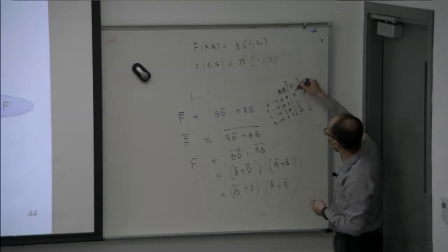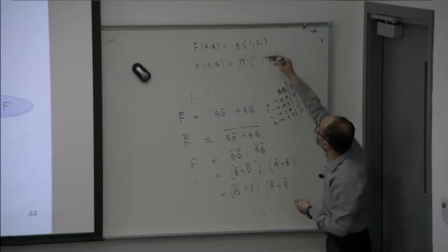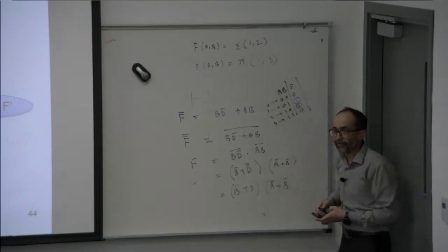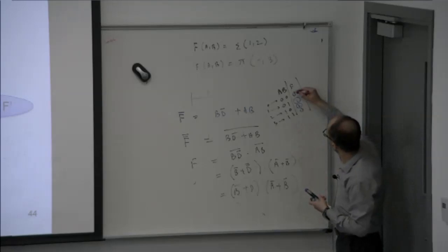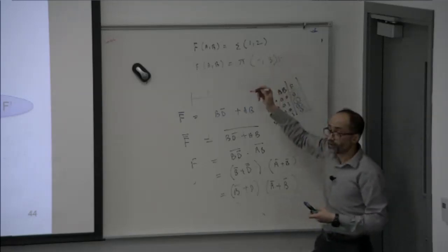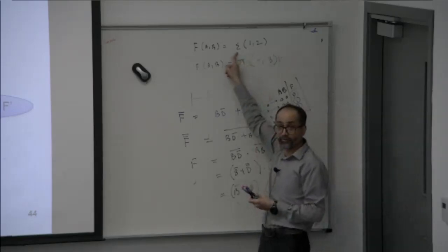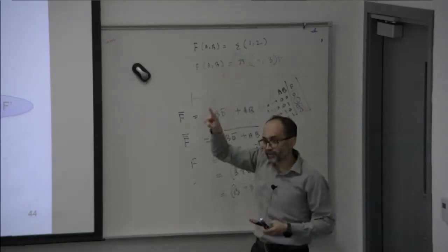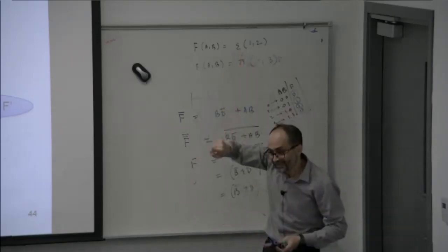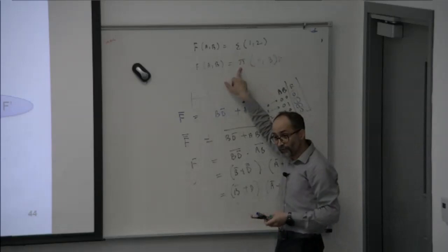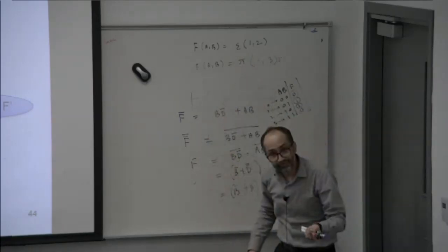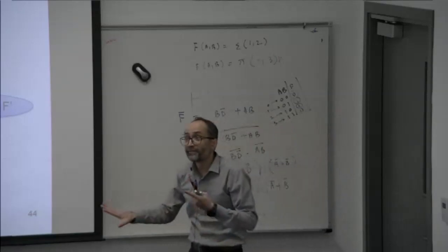So now we write this f in the sigma form. So sigma form is what? 1 and 2, and pi form is what? 0 and 3. So this is the pi form. So you can convert. I may give you the sigma form and ask for the POS expression, or give you the sigma form and ask for the SOP expression. I may give you the pi form and ask for the SOP expression. So all of the possible combinations are there.